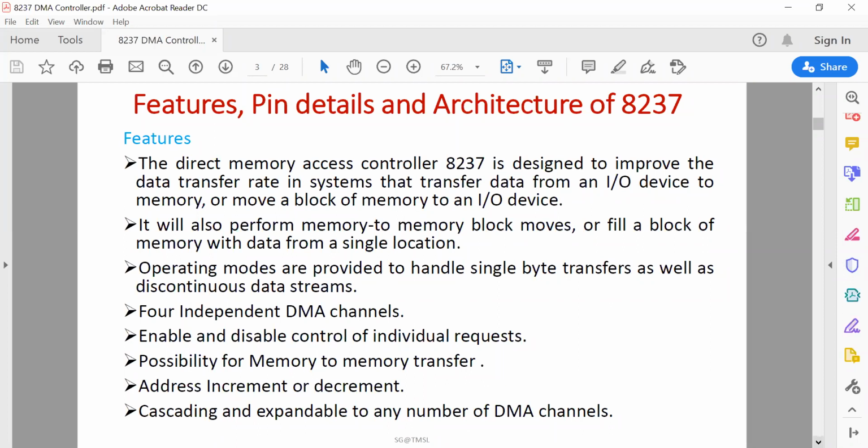Once the DMA controller has finished transferring data into or out of memory, it gives control back to the microprocessor. The microprocessor cannot accomplish any other function when a DMA transfer is taking place, for two reasons. First, the microprocessor memory is being used for the data transfer, so it is not available to supply program instructions or receive the results of computations. Second, the typical DMA process requires the microprocessor to place its address bus and data bus in a high impedance state.